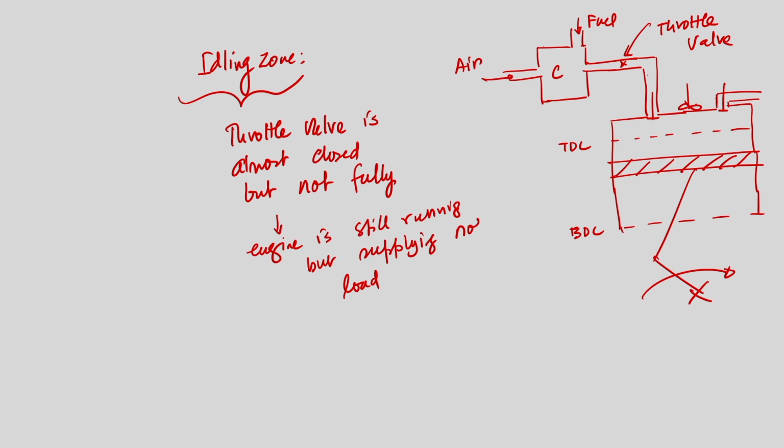So, in that zone, what will be the requirement of fuel air ratio? That is very important, that we should know. Since we are not taking any load from the engine, it is quite expected that the fuel air ratio supplied during this zone of operation will not be very high, but that is not the case, that we will discuss today. Now, next is the very important cruising zone.